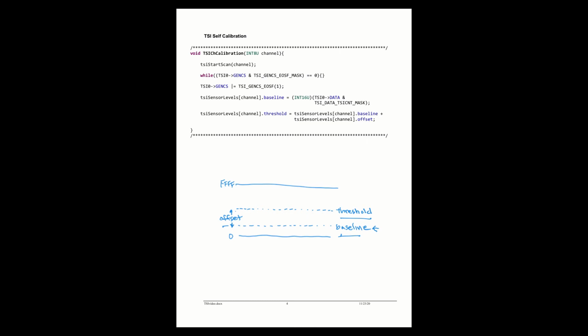If, say, the count is up here, you could say, well, wait a minute, the count is above the threshold. It looks like someone's touching the sensor, so let's not do a calibration now. If the count's down here in the baseline, it can say, okay, this is a good time to do a calibration, and then maybe it changes this baseline a little bit.